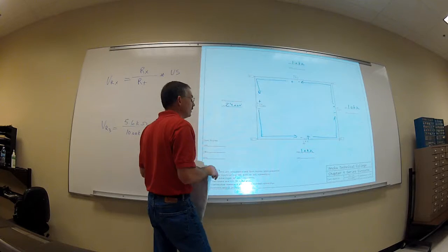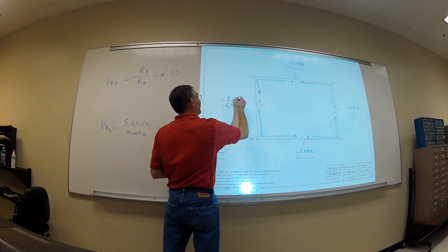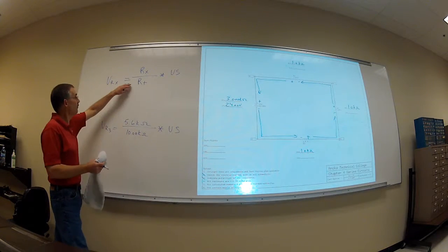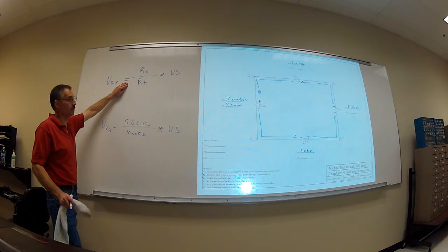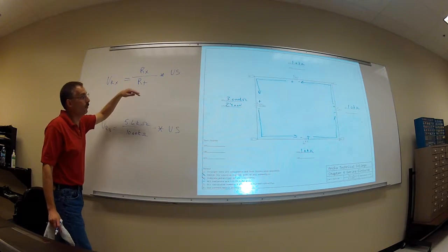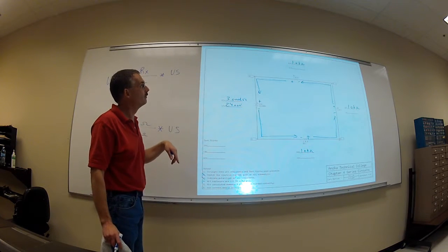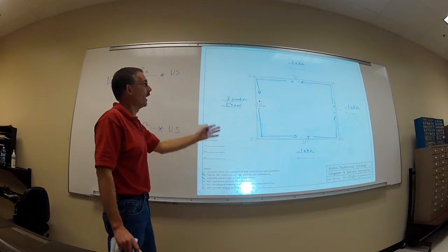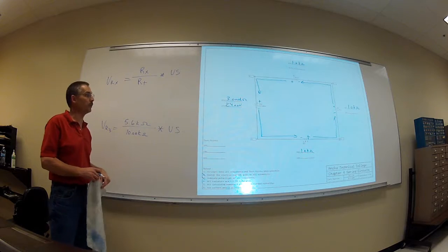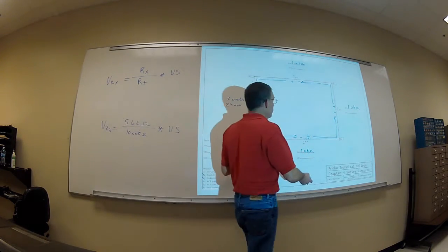What's our resistance total going to be? 3 kilo ohms. Okay. So we said that all our voltages are going to drop proportionally across our components. If every one of them is a 1 kilo ohm, which one's going to drop the most amount of voltage? Equal. They're all going to be equal, right? So we got 3 different components. They're all equal to 1 kilo ohm. So how much voltage is going to be dropped across each one of these components? 8.